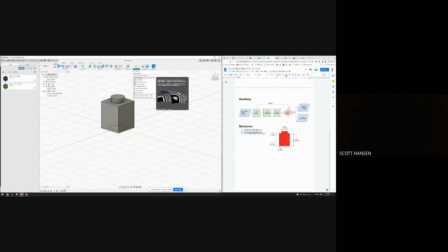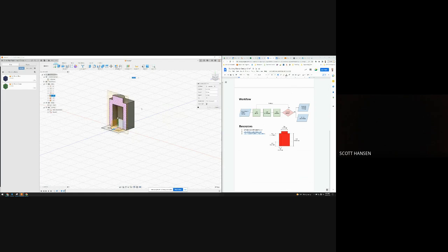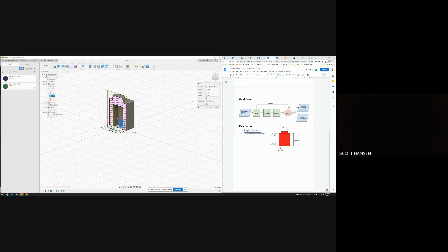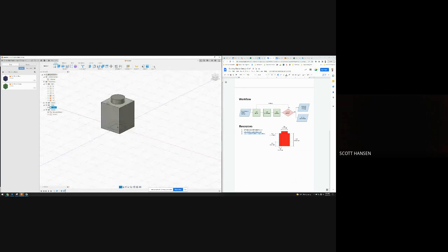And we can do a couple things to view this and modify this. If you go to inspect, we can do a section analysis. Let me select one of my default planes. Let me grab, there we go, the XY plane. And remember, that lets you kind of see a slice into the object and view part of the object. And you can, under analysis, click your section view and change where that slice is taken. And you can hide that section once you're done viewing that. So that's one way to check and see that the inside of your block makes sense.